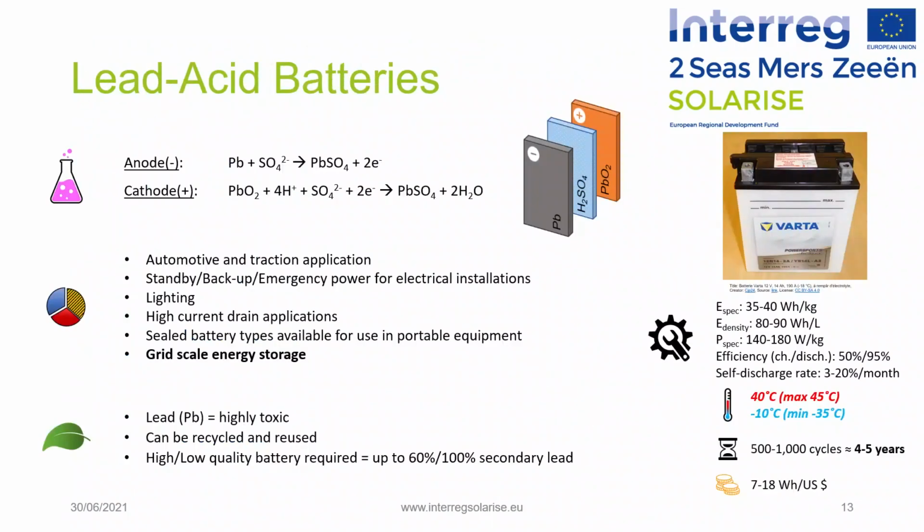The lead-acid battery is the first type of rechargeable battery ever created, in 1859 by the French physicist Gaston Planté. They are composed of a lead electrode and another one in lead oxide and an electrolyte of aqueous sulfuric acid. Compared to newer types of rechargeable batteries, lead-acid batteries have one of the lowest energy densities. Despite this, their ability to deliver high current means that the cells have a relatively high power-to-weight ratio. These characteristics, along with their low cost, make them attractive to use in motor vehicles to provide the high current required by the starter motors.